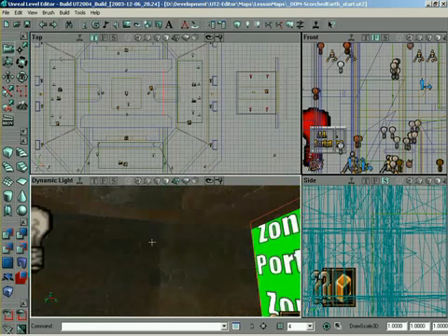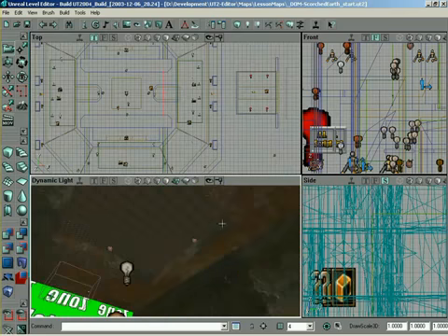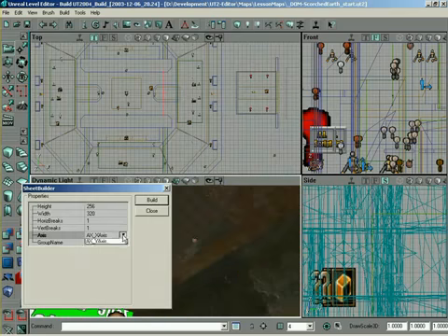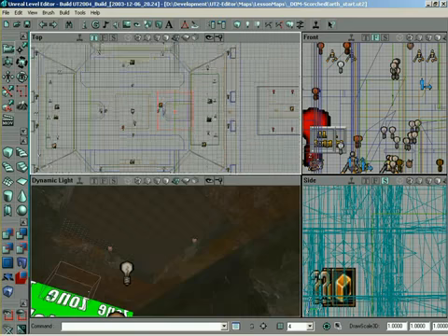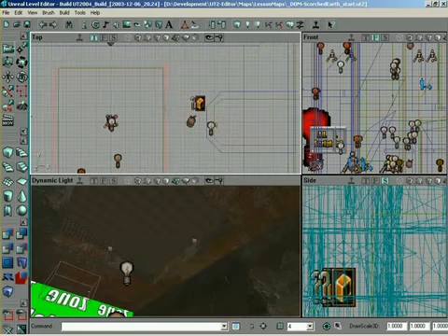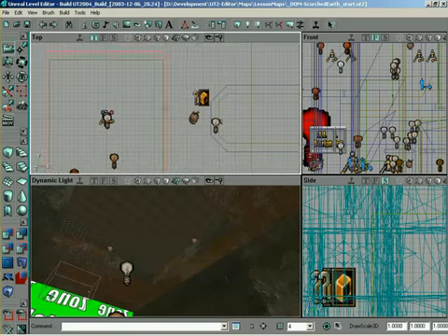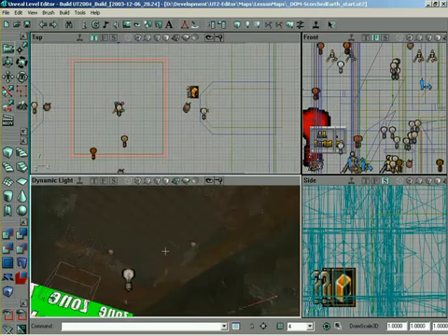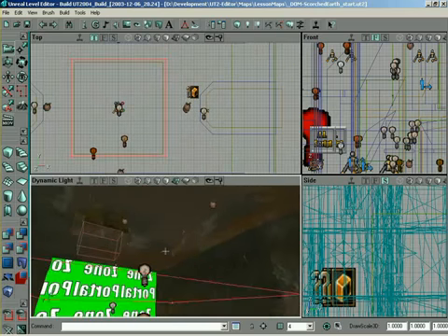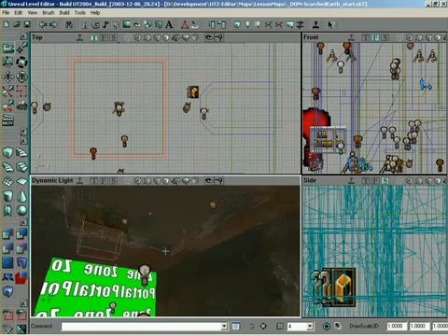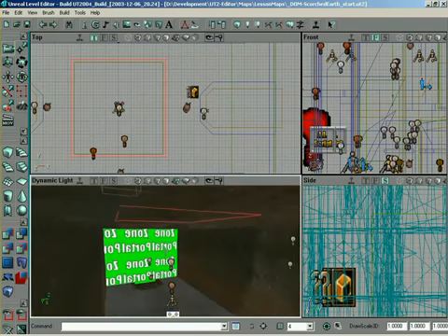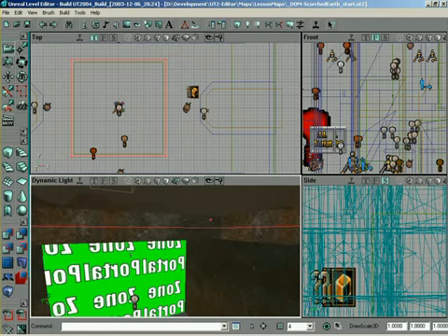Now, the last thing we have to worry about is the little hole in the ceiling, so let me switch the brush axis to horizontal, and maybe change the height and width to 240. So with 240, that should more than cover the opening here. Just align that in a little bit, like such. And I'm actually going to use the perspective here, holding Control and both mouse buttons to constrain to Z, just so I can kind of visually line it up. Right, it looks like that's going to work just fine.